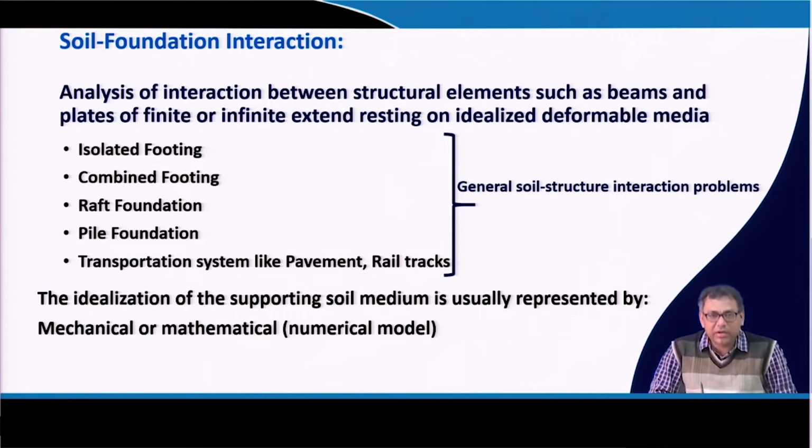Here we will consider the mechanical part, that means the soil will be idealized by different mechanical components like spring, dashpot or both, and the foundation will be idealized either by beam or plates. Then we will consider the interaction between this beam and those mechanical elements, and the beam can be infinite or finite depending upon which type of problem we are solving.